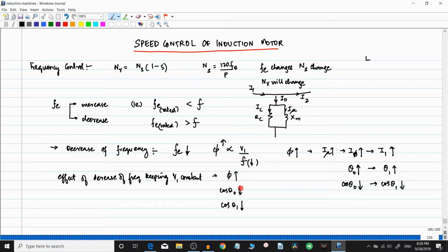One, low power factor means it is a problem in the system. Okay, see, low power factor loads draw a lot of magnetizing current. It is not good for the bus bar to draw such a large amount of magnetizing current in general. Okay, so now if flux rises, what is the problem? So when flux rises, the motor goes under deep saturation. The motor core goes under deep saturation.